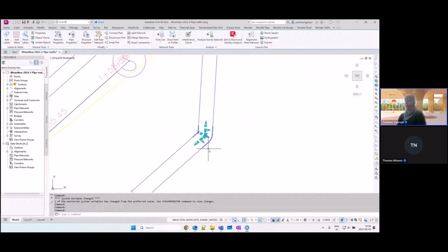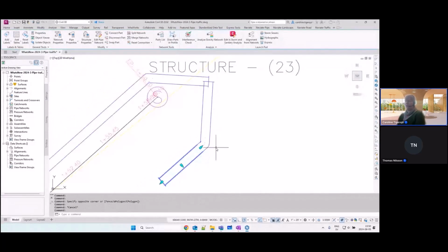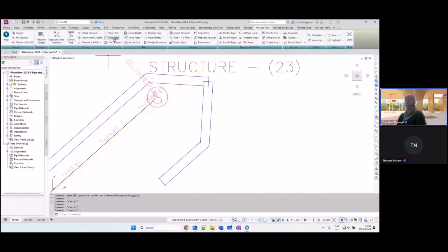So I have the different objects. This one will actually be the bend. These will be connected and be considered the bend. The rest will be the pipe objects. So this is a way of creating pressurized pipe, water or district heating, with gravity pipes, which gives us benefits. The big benefit is that I have all the dimensions that I need. I don't need to create these objects one by one. So it's a way of using gravity pipes, but still being able to create them at specific angles and specific lengths.